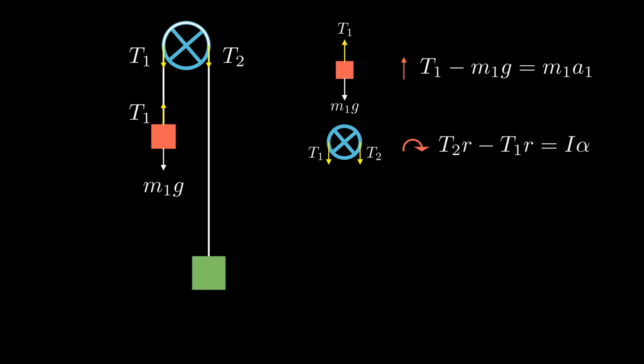It is important to note that the weight of the pulley and the reaction force do not contribute to the rotational motion because they both pass through the center of the pulley, and therefore we can ignore them when writing the equation of rotation.